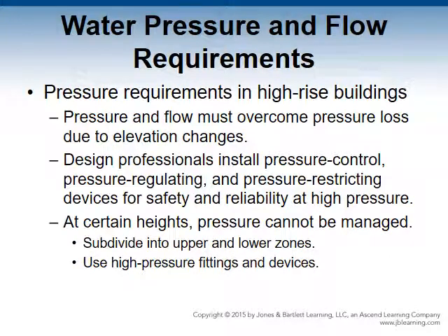Pressure requirements in high-rise buildings. Pressure and flow must overcome pressure loss due to elevation changes, making system design in these buildings a challenge. To get pressure to the top, pressures on the lower levels must be much greater. Some components are rated up to 350 psi.